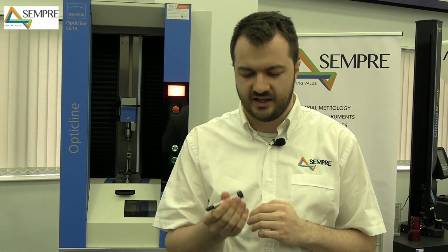So today we've been using this bolt, so shoulder bolt, to demonstrate some of the features, and you can tell that it's got a centre at the top here where an Allen key would fit, but it has no centre in the end there. And you can tell that this could cause an issue if you don't have the correct centres. So you may put a cone centre in the base, but then you'd need to use a female centre at the top. You can see in the machine that we've loaded in a female centre at the top,